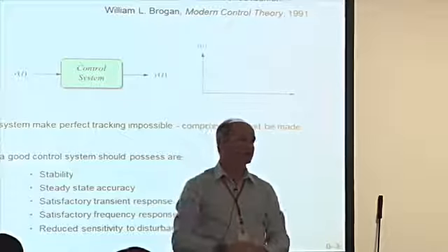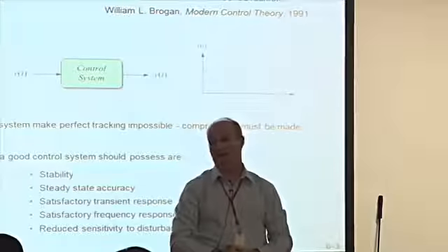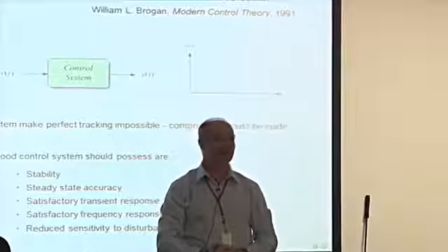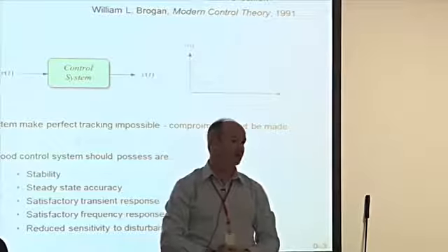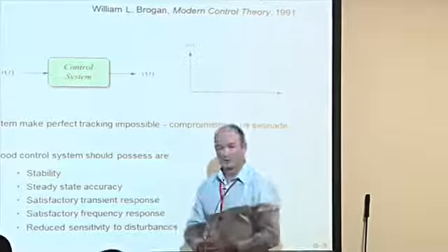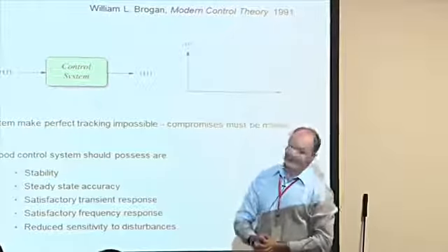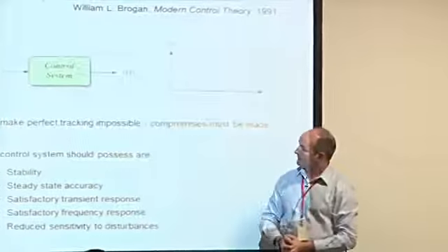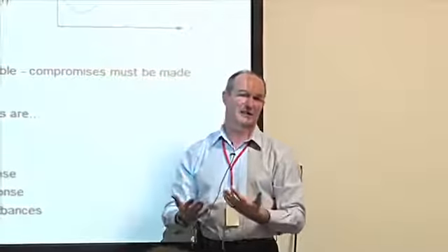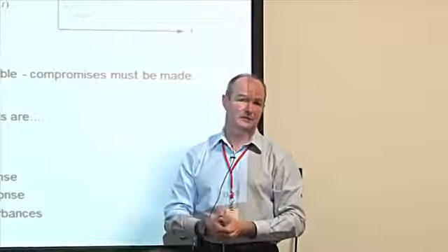In the language of control, that's known as perfect reference tracking. As I'm sure you know, it is impossible to achieve. To achieve that, our system would have to have infinite bandwidth. No systems have that. So we have to make some compromises. Now, among the compromises that we make are, well, finite bandwidth, finite speed, many other things. And now we have to somehow specify how good we want our system to be.